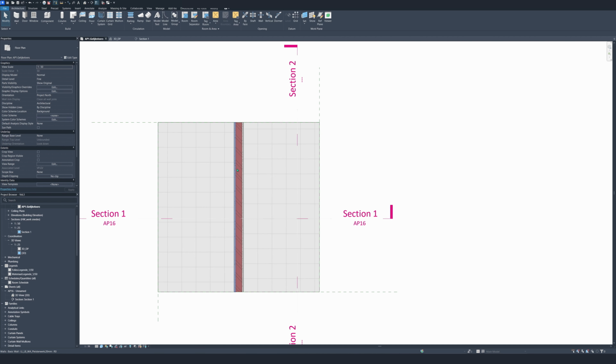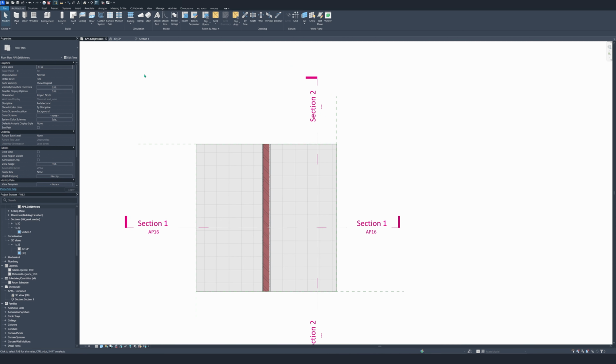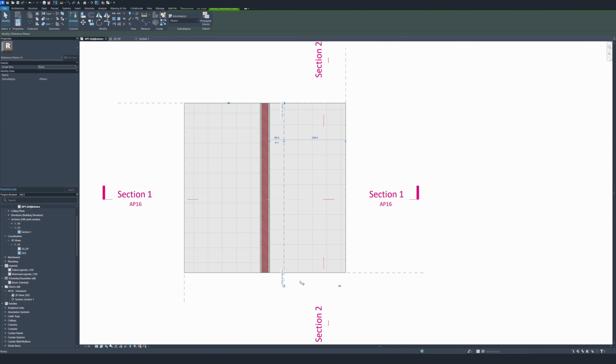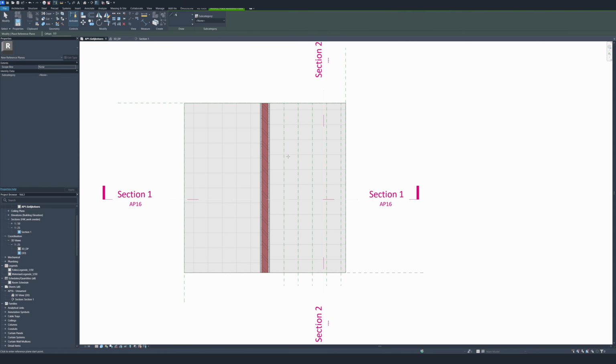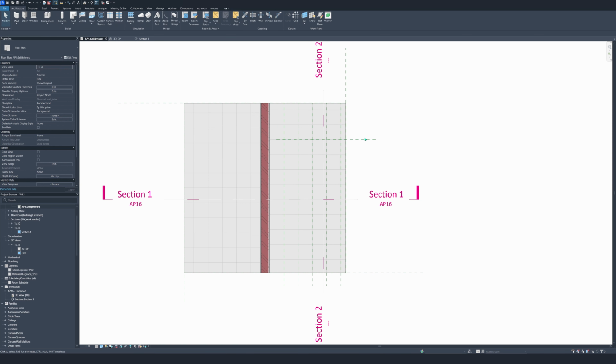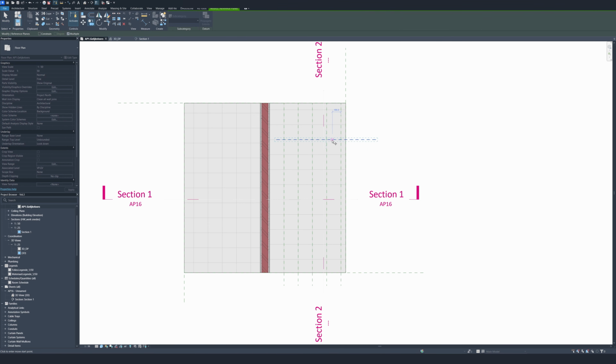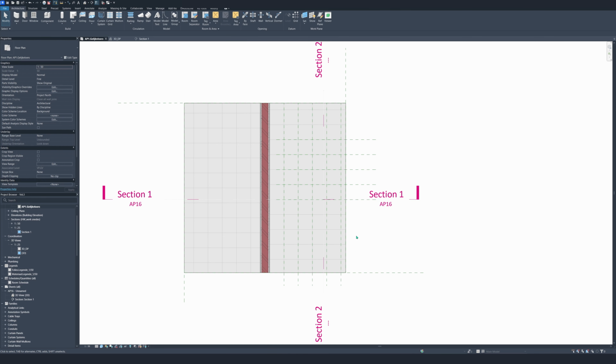So for that, again to the ground floor. But here we're gonna make use of the reference plane on the architecture tab. So click on the reference plane. Now we're gonna make reference planes like here. Now copy it. Like 1, 2, 3, 4. Now we do the same for the horizontals. Now select it, copy it by 1, 2, 3, and 4. This will do, I guess.